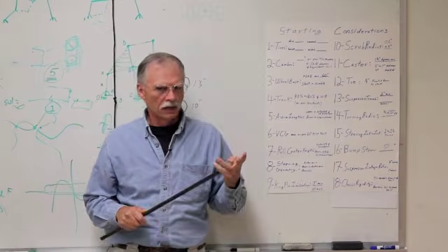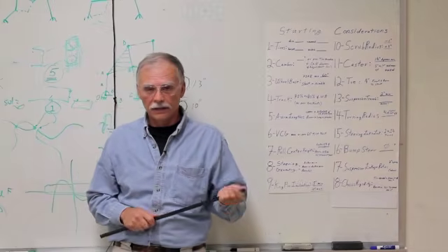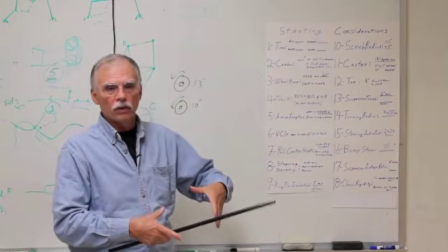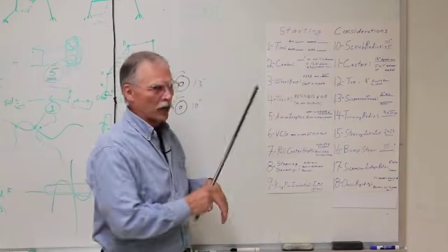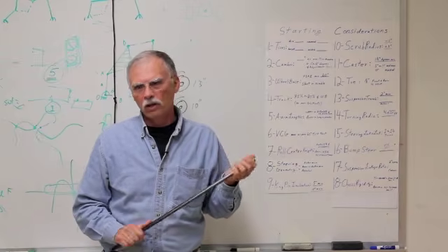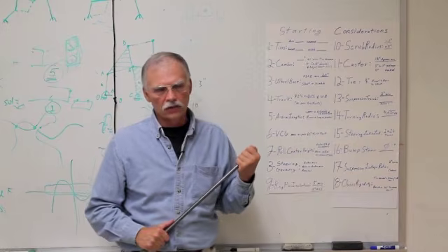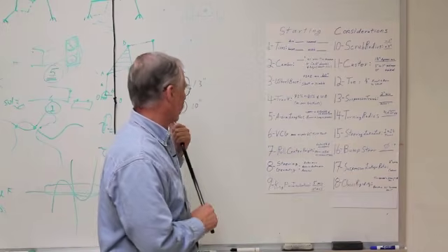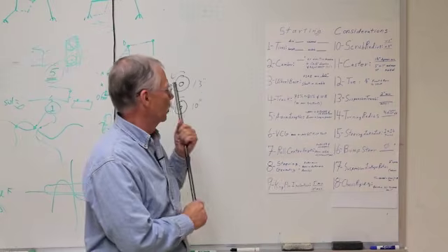Well, what's the downside? If there's an upside, there's always a downside. The downside is the smaller inside of the wheel makes fitting brakes, uprights, steering linkages much more difficult. The packaging of the steering and braking system is more difficult. Can be done, of course, but it's easier in a 13.